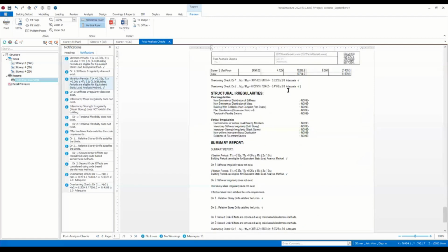And next up is the summary table for structural irregularities. So we list all of the potential structural irregularities and their existence information in the model. So we don't have any irregularities for this model. We have looked at the report, and I have shown you that some of them are, for example, soft story irregularities calculated by the software, and some of them are not. We haven't seen them in this report.